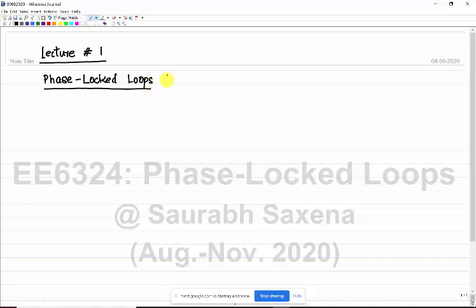What I can tell you about phase lock loops, just to begin with, is that this is a block which generates some kind of periodic signal. So we have a PLL as a block and the output of this block is going to be a periodic signal. I wrote periodic signal, not a particular clock or sine wave, because you can have periodicity for different kinds of signals.